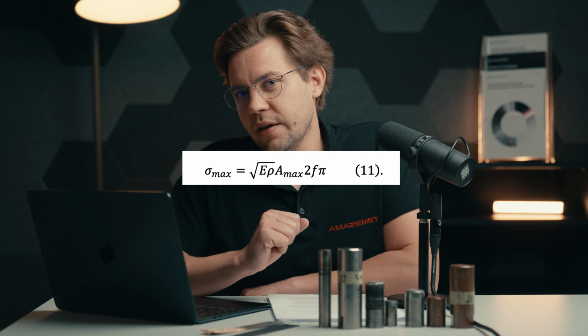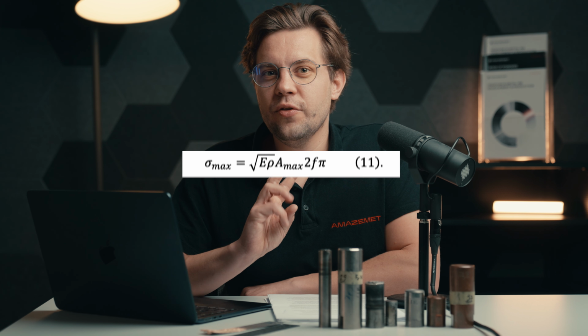If we want to calculate what the stress is, there are three most important factors. First, the amplitude. It is basically linear with the amplitude. The higher the amplitude, the higher the stress. But there we have to bear in mind the material. If we think about the spring, the Sonotrode, as our model, there are two main material properties that determine what the stress inside is: stiffness, our Young modulus, and density.